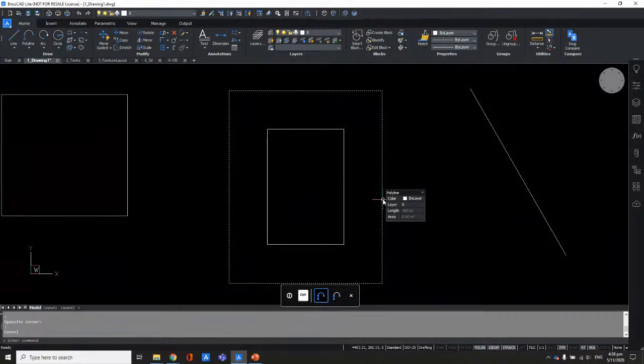It says I and CTRL, which is control, and that CTRL button means that I am able to select this full polyline. As you see, there's a blue square highlighted there. But if I click control, it gives me an option of selecting this segment only. It moves to the next selection type that it can do. I'm now pressing on control.